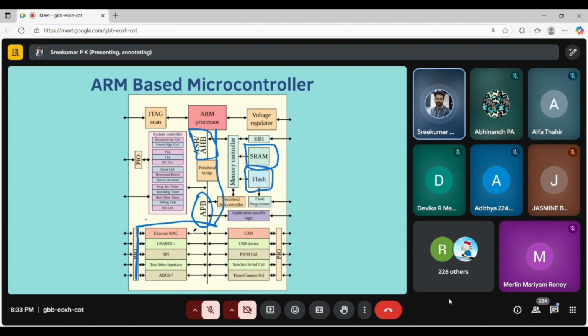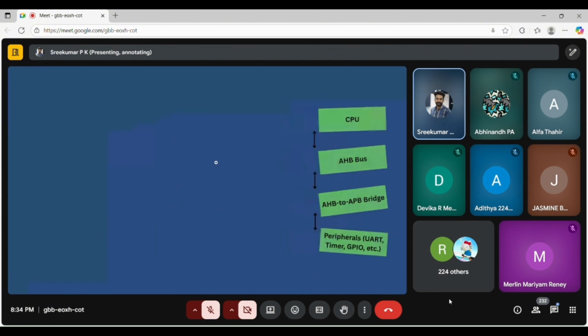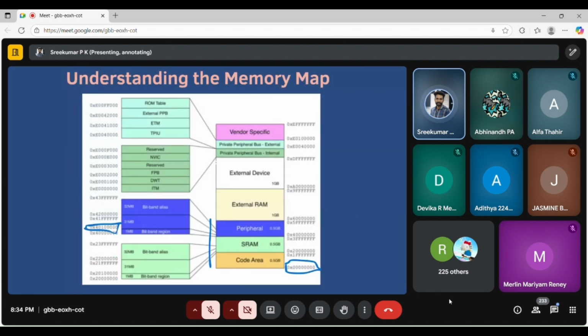So what it does is that the CPU knows the address of that particular GPIO. It will write 1 and 0 in between a particular duration. That is what the delay does. So what it is doing is writing a 1 and 0 to an address that is somewhat like this 32-bit address. So this is what happens inside when an LED blinks. So someone is writing, not someone, the CPU is writing 1 and 0 over here in between that delay.